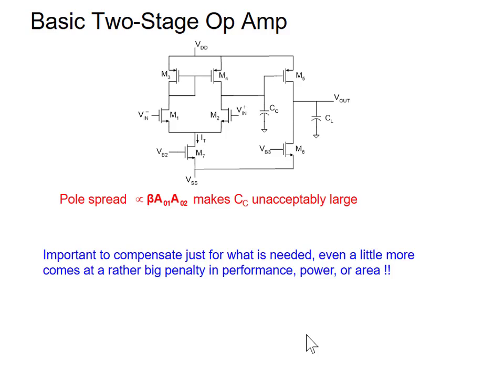And if you realize that we're going to have applications that have beta of 0.5 and beta of 0.1 and beta of 0.05 and beta of 0.01, then you can say, well, look at this opportunity. We've got 4,000 catalog op amps now that are compensated for beta equals 1. I want another 4,000 op amps compensated for beta of 0.5. And another 4,000 op amps compensated for beta of 0.1. Would you be able to build better systems? Absolutely yes.